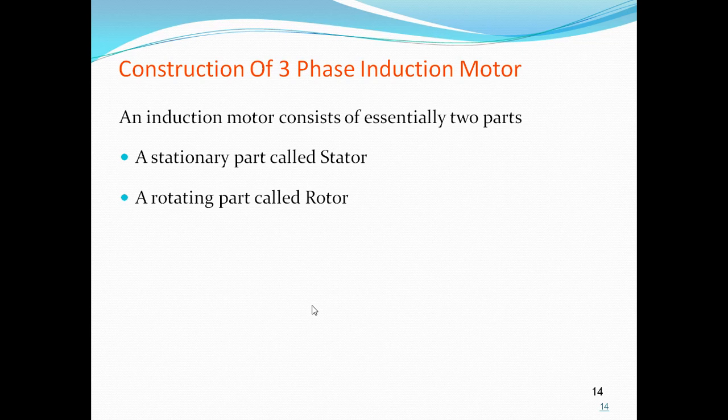So in this case, phase wound rotor, the three phases are star connected internally and the other three winding ends are brought out and connected to three insulated slip rings mounted on the same shaft with brushes resting on them.